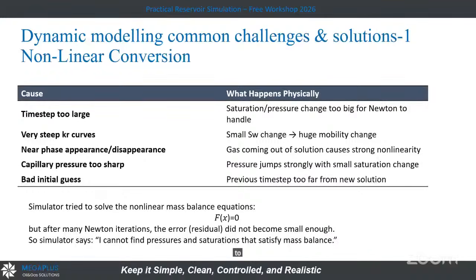As I told you before the break, the simulator doesn't have input inserted by me. It depends on the output of the neighbor cell, so a lot of iterations happen. If, as an example, you make the time step too large relative to the model run, this sudden change will give a huge number that's far from the right one. We will have a lot of iterations, and maybe from too many iterations the model will not work, or will be very slow in running.